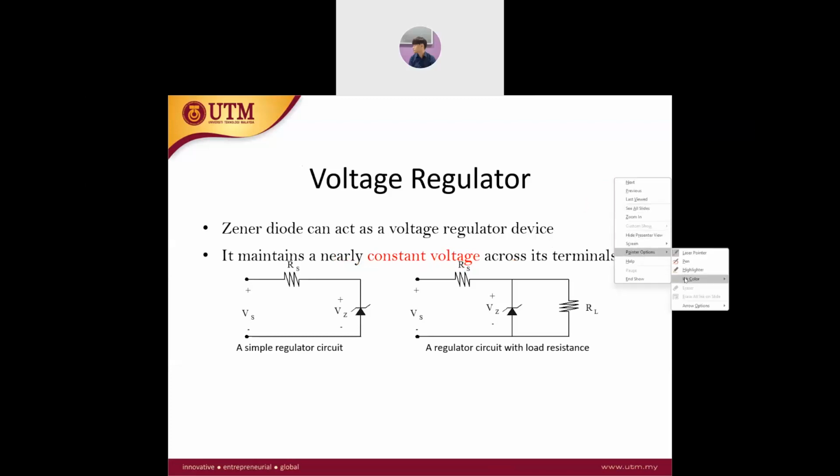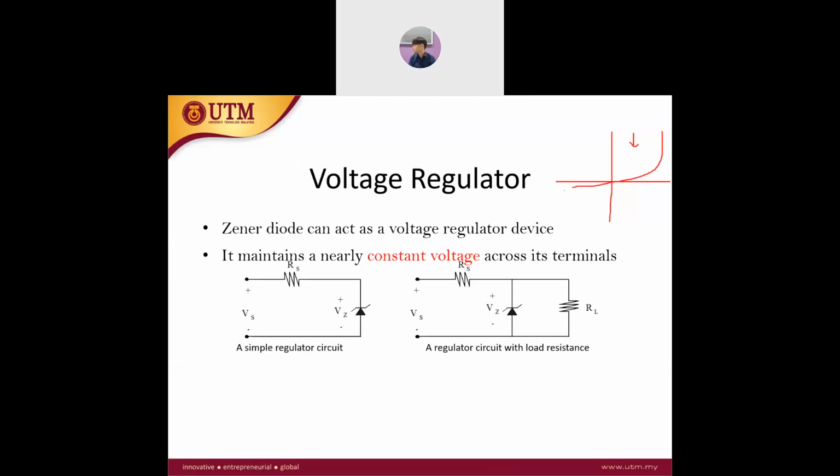As we know, we firstly use the Zener diode for operation in the breakdown region, which is in the reverse bias region. So here it's going to be normal diode operation, and here is actually our interest for the Zener diode operation. This is the start of VZ minimum. This is the current for the reverse currents.